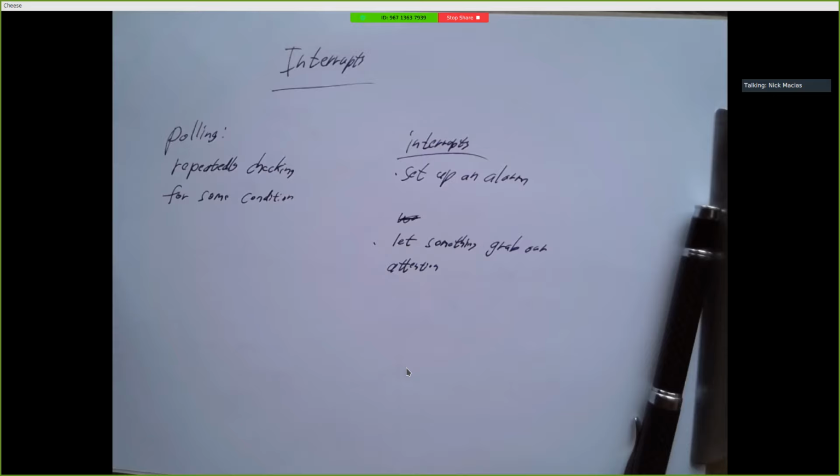The PIC processor has 2 priority levels. Larger scale, more complex machines might have 31 priority levels. Okay, it's a feature of the architecture. But all of these systems have in common the fact that you need to set up the system, right? You need to control what's going to be able to get your attention and how high priority that event will be. And you need to turn on this whole system to begin with, because by default, interrupts aren't enabled on the PIC. Right? The things that can generate interrupts will not generate interrupts unless you do some work to say, I want interrupts to be allowed.